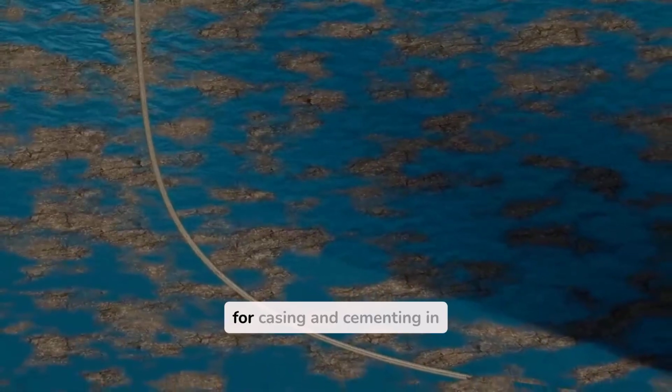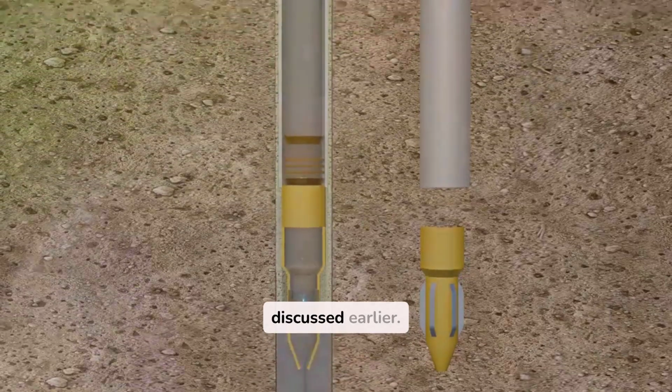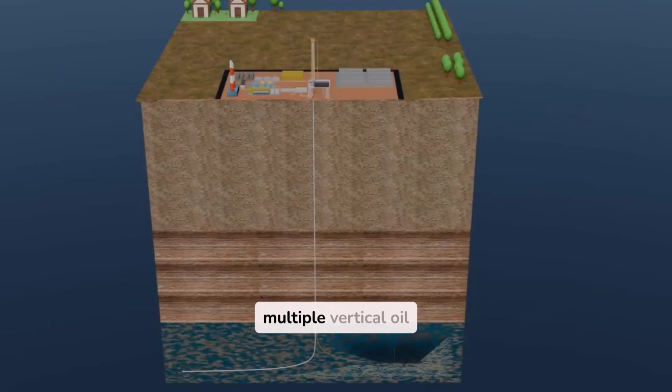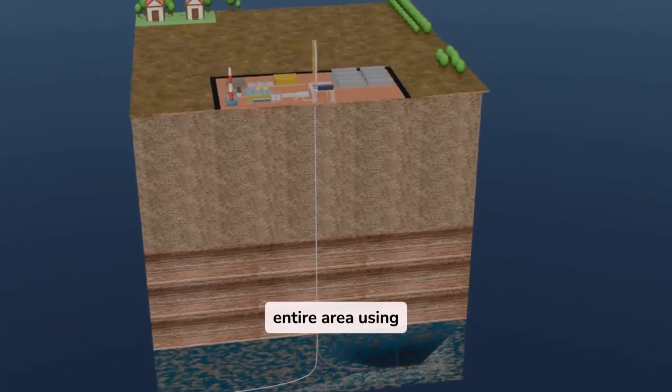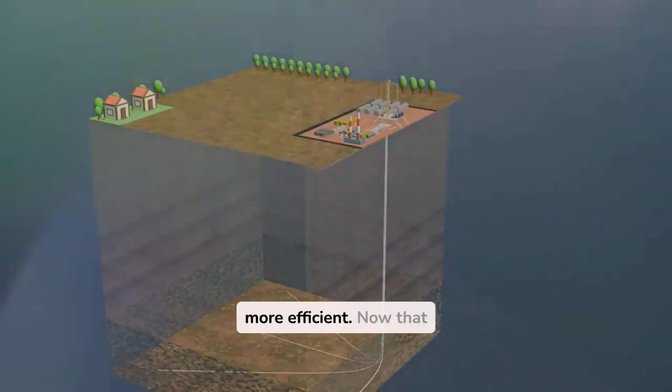The processes for casing and cementing in the horizontal section are the same as those used in the vertical sections we discussed earlier. Using this technique, if there is an area of about 20 square kilometers, multiple vertical oil rigs would traditionally be needed. However, with horizontal drilling, oil can now be extracted from the entire area using a single surface location, making the process far more efficient.